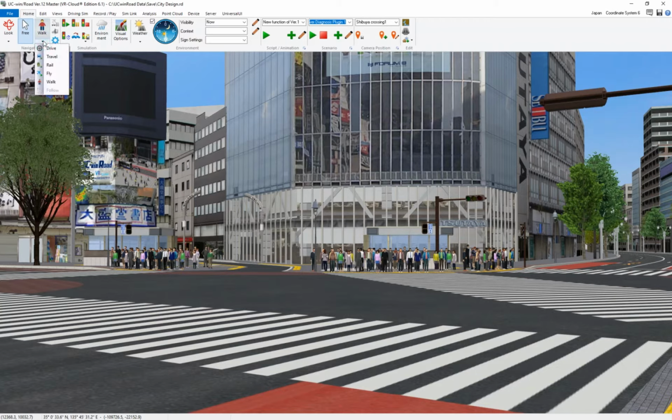The other navigation modes are linked to some other functionality, like for example driving, traveling on the road, on a railway. You can fly along a flight path, walk anywhere, but you are walking on the ground. You cannot move anywhere. And we have what we call follow, which is to follow an object in the scene. Some of these modes are enabled only when you created a road, for example, or a flight path. If you did not create a road or a flight path, these modes will be deactivated. Okay, so you can switch between the free and these modes.